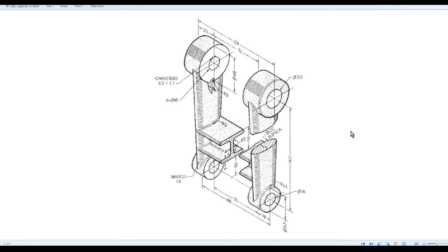As we have been explaining in the last few weeks, for symmetrical objects, the best way to tackle something of this sort is to complete one half and then use the powerful mirroring tools to complete the opposite end of it. There are features such as the holes that are slightly different. For example, this hole here is 22 millimeters as opposed to all the other holes, which are 16 millimeters. And the top hole here in the top boss actually has a keyway through it. So we are having to add additional features, but we will go about doing it step by step.